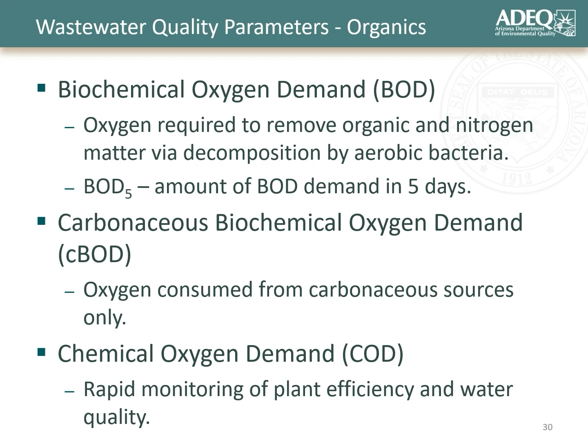Finally, there's chemical oxygen demand, which is a rapid test, taking hours rather than 5 days as the BOD test may. And it measures all oxidizable compounds within your sample. While it is an overestimation of the potential impact if you discharge to a stream, the benefit is that you can sample it and get results within a few hours. It's a lot faster. You can respond a little bit quicker.